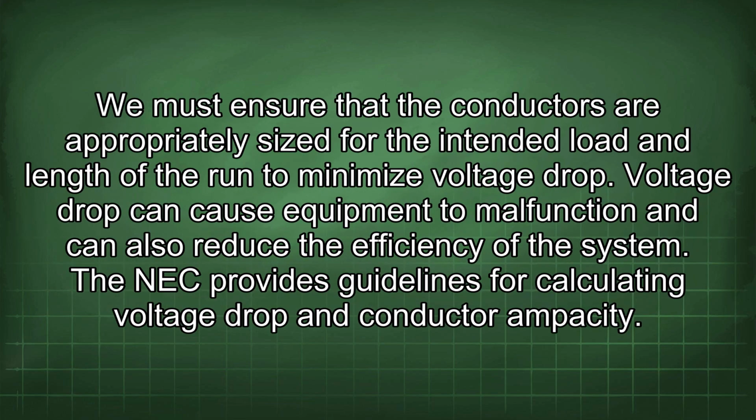We must ensure that the conductors are appropriately sized for the intended load and length of the run to minimize voltage drop. Voltage drop can cause equipment to malfunction and can also reduce the efficiency of the system. The NEC provides guidelines for calculating voltage drop and conductor ampacity.